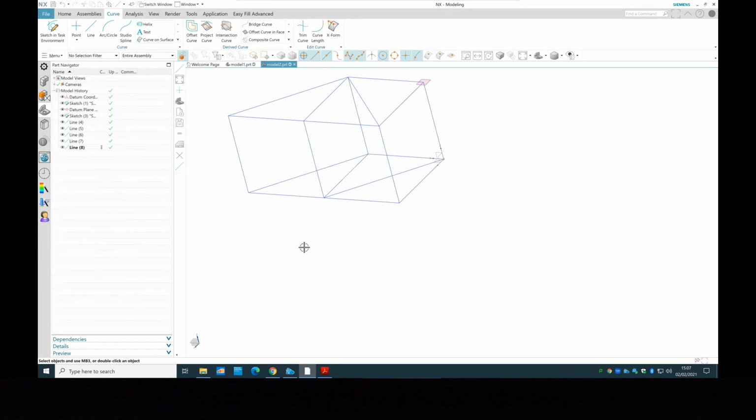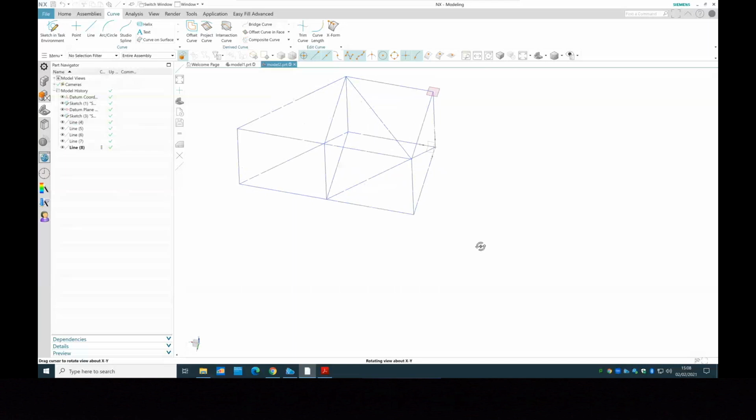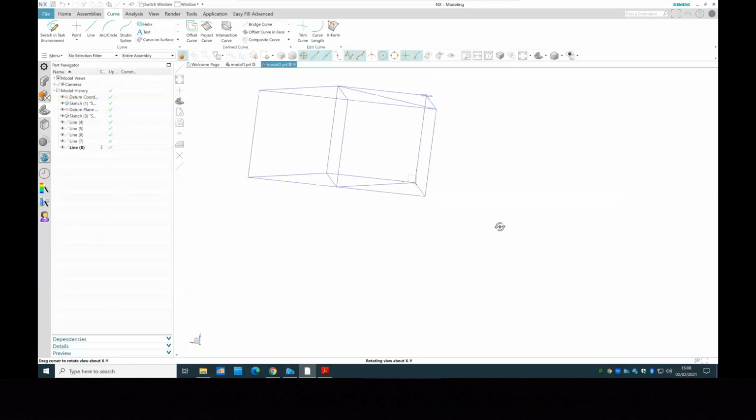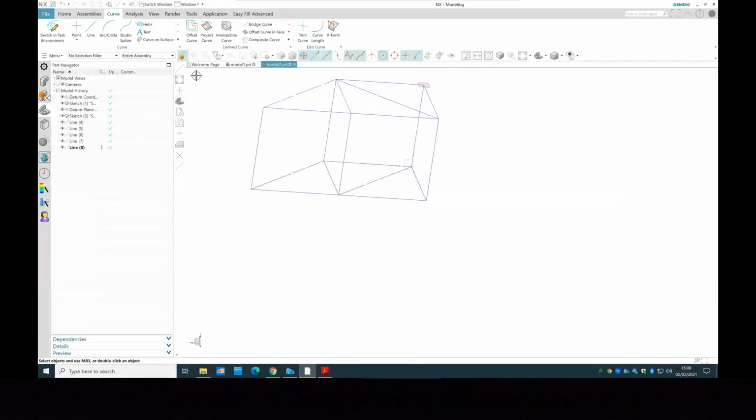So you put it in isometric, and then you decide where to go. Yes. Exactly. Yeah, because if you don't put in the isometric, whenever you create a 3D sketch, it will try to guess what kind of planes you want to draw in it. So technically, every sort of these is attached to a plane which is not visualized here. So it's important to put it into the isometric or the different views so you would be able to see it properly. And there are 2 more lines that I want to add.